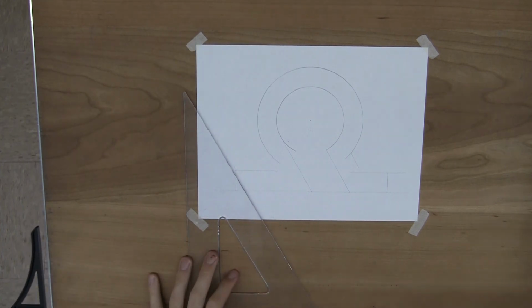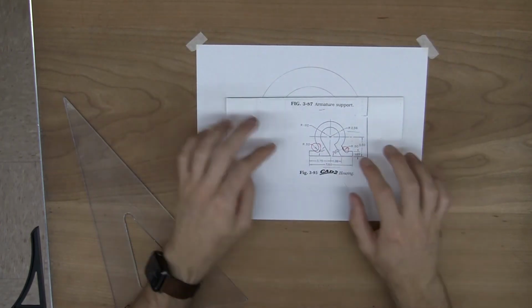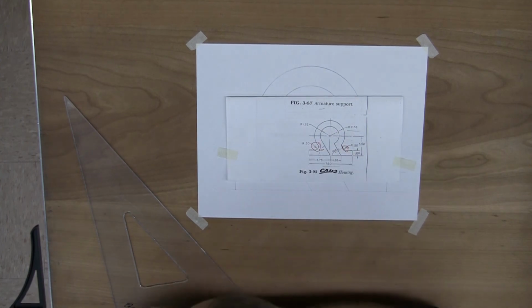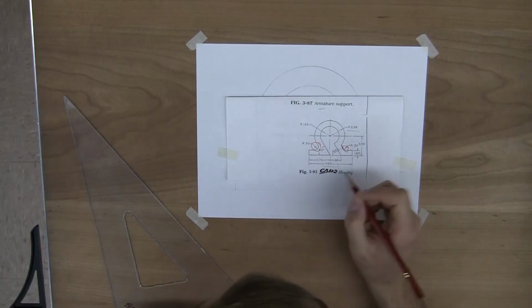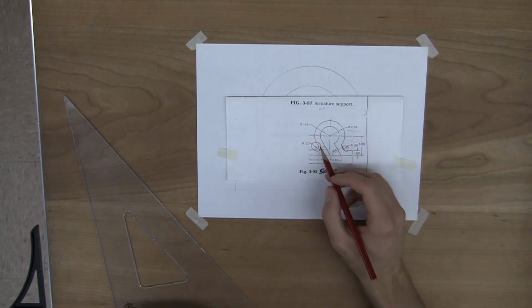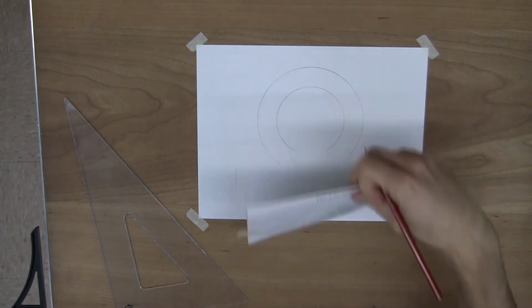Okay. These corners, it's a radius, it's an arc. The radius is 1/2 inch, but there's no center point. There's no dimensions given to how to find that center point, left, right, vertically, horizontally. We don't know where it is. But we do know that it's tangent to this line and this arc.